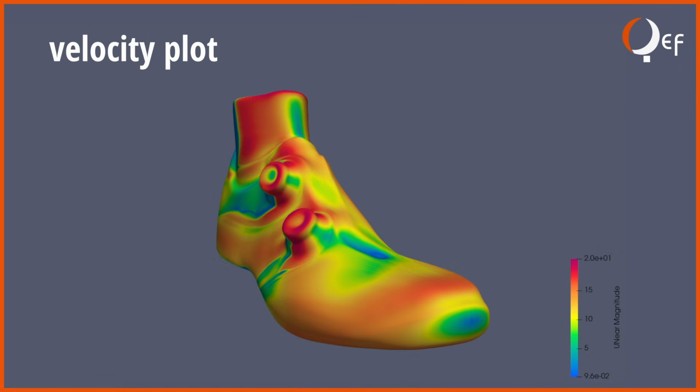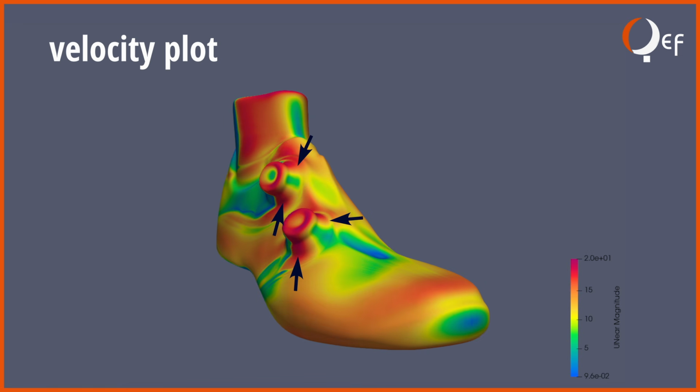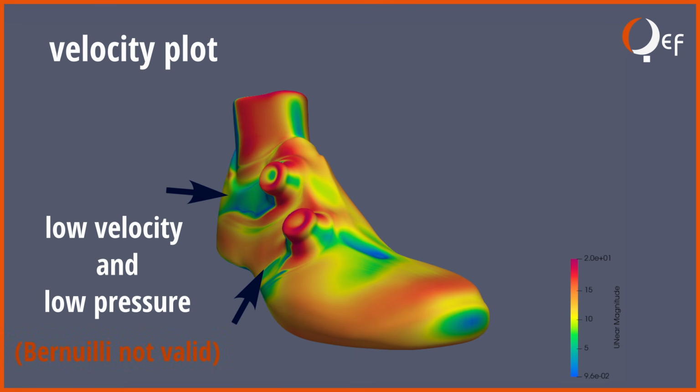Let's now examine the scenario involving the two dials. The air experiences a slowdown as it encounters these frontal areas, leading to a rise in pressure. High pressure on the frontal area means drag, which constitutes the first negative effect of the dials. The airflow then gains velocity around the dials as it would around a standard cylindrical shaped object. Finally, the flow slows down and creates a large depression zone, which generates additional drag.